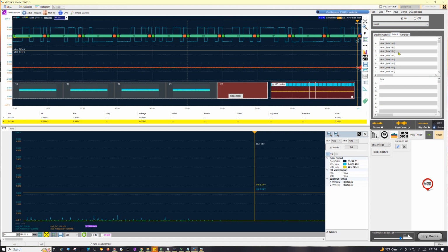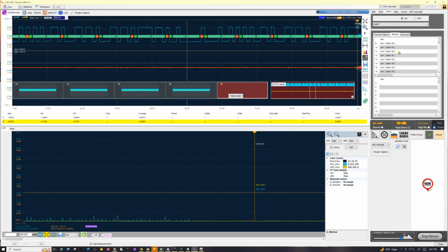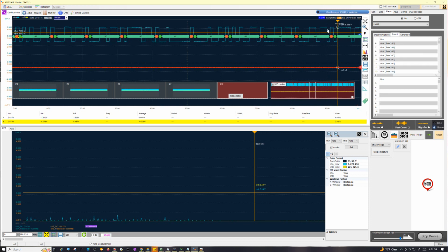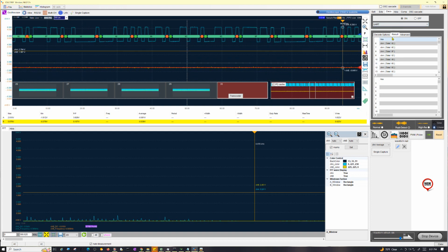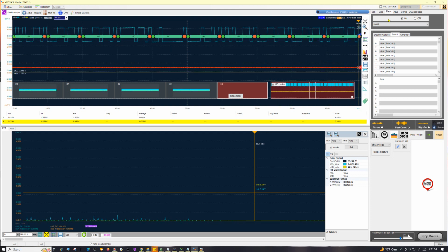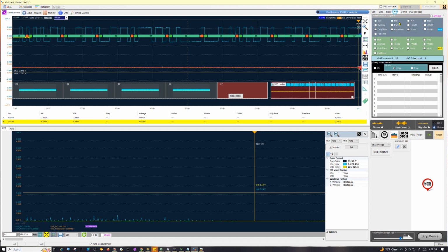Okay, you can kind of see the result. And this message is actually hello is what it is. So it's just hello over and over and over again. That's coming from the analog discovery. But that kind of shows you how the decoder works. So you've got the data bit, your stop bit, your start bit, and no parity in this. But at any rate, useful.